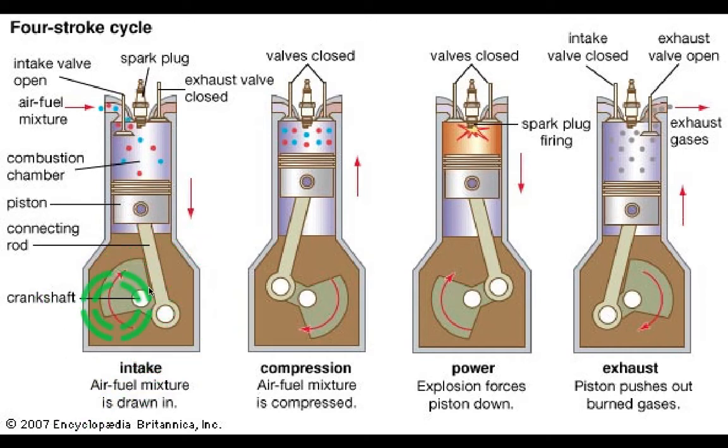360 degrees makes one complete circle. So half a circle is 180 degrees. So when this is on TDC, this thing is gonna go all the way till here. So when it comes down, it's gonna reach here, right? So that is your 180 degrees. Then again, it's gonna go up. So one revolution of the crankshaft, because the flywheel is connected on one end of the engine, and on the other end is your main pulley and your other pulleys. The flywheel is hooked right onto your transmission.